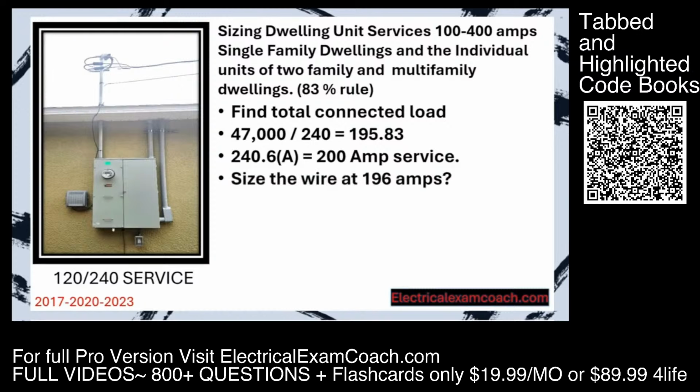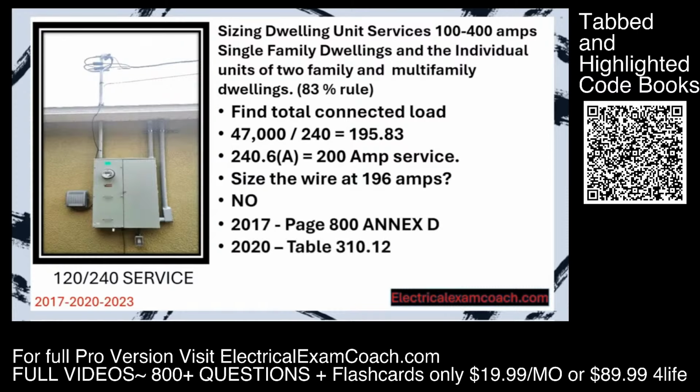Now the next step normally would be to size the wire at 196 amps, right? That's our known load. We can just follow our normal ampacity rules. Well, not with services that are between 1 and 400 amps. And let me show you what I mean. Let's all head to page 800 if you're in the 17, this table if you're in the 20, and this table if you're in the 2023.